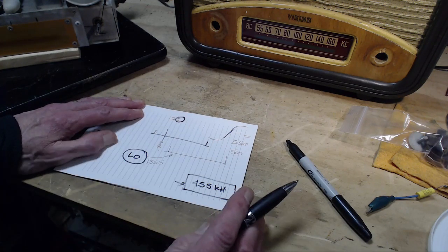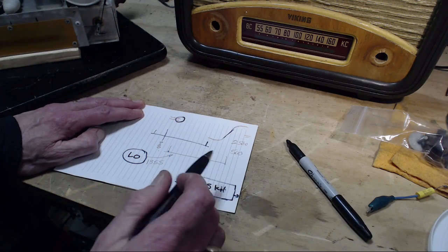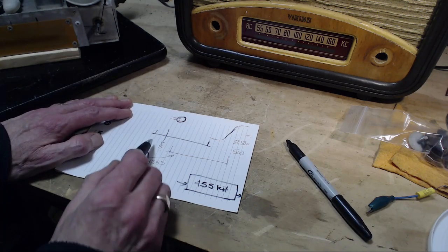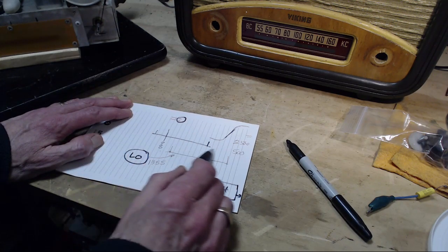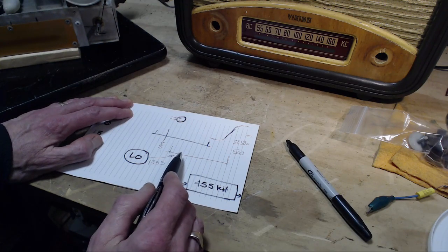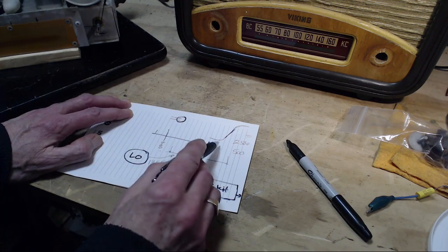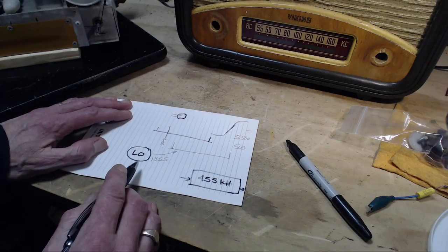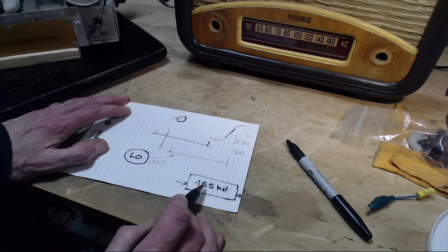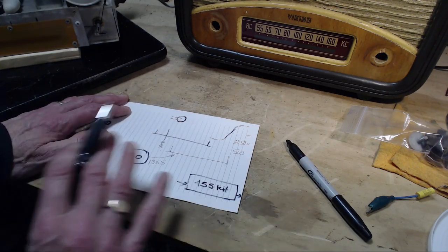It's mixing with everything all the time. So the output of the tube, and I'm putting quotes around it, is this entire thing shifted 455 kilohertz. I really didn't draw the output of this. But a lot of those other signals, the ones that are far away from 455, are being suppressed in a number of different ways.